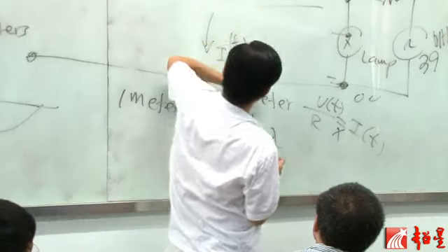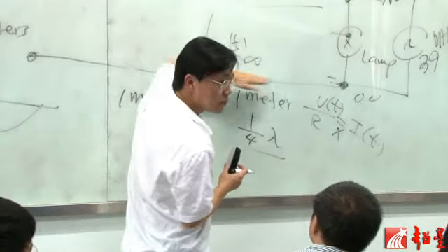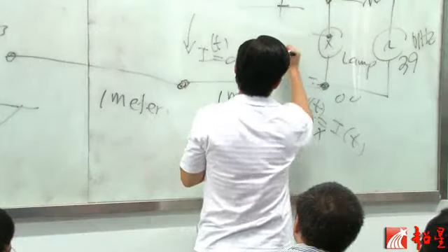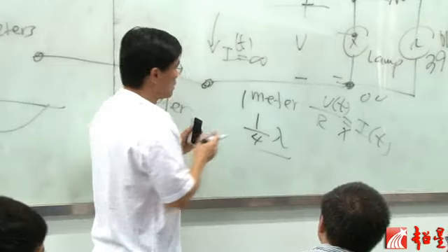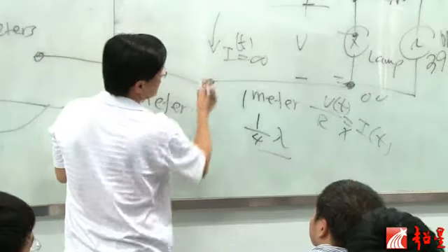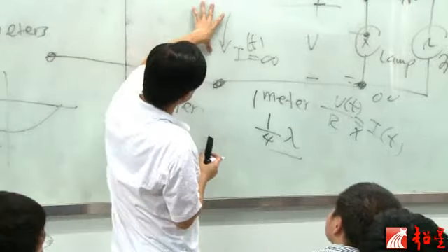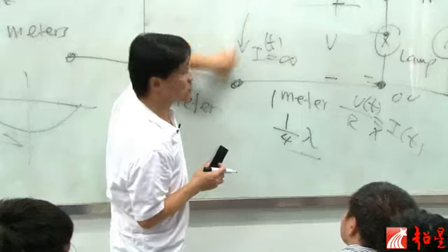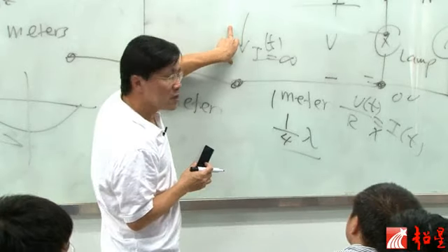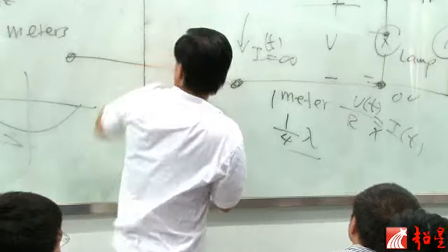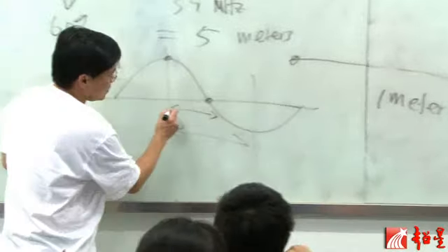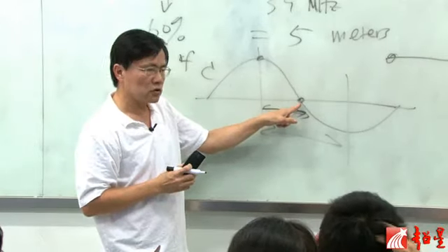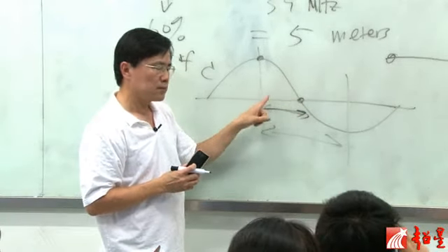This voltage is compared to this line. At this point, the voltage is between these two. That's the voltage, and this is distance in space. Because this end is open circuit, the voltage will reach its maximum because there's no current here. And when the voltage reaches maximum here, then 1/4 of the distance away, that voltage is 0.